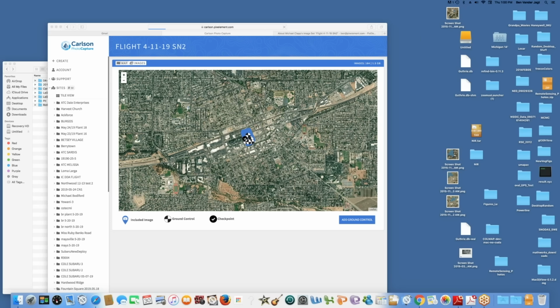But you have to remember, this is kinematic. The drone is flying, and people are moving around. You don't have the opportunity to sit on a point and make sure you're getting sub 2 centimeter accuracy. So I can't say that you wouldn't get 1 centimeter. It's possible, but I wouldn't guarantee that you will, just because the accuracy of the observations themselves is not consistently 1 centimeter.